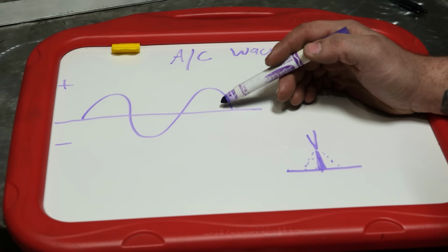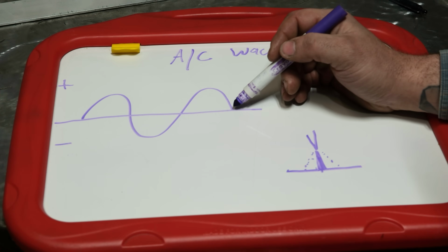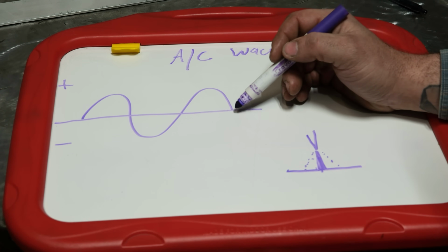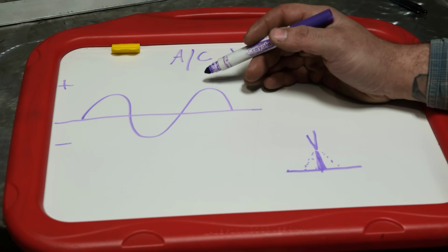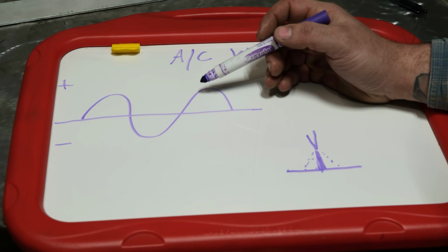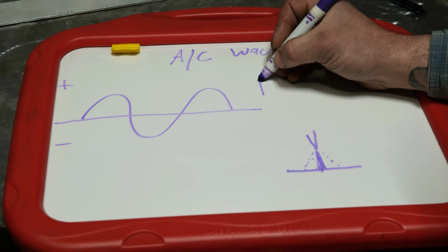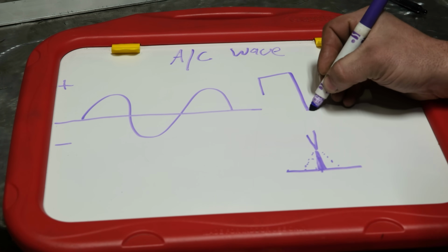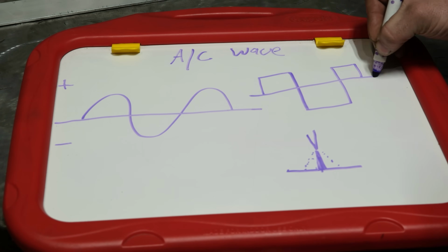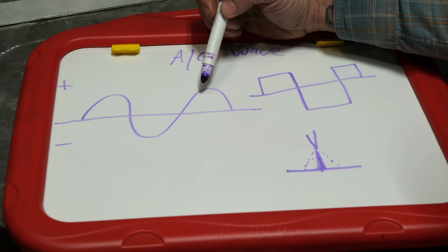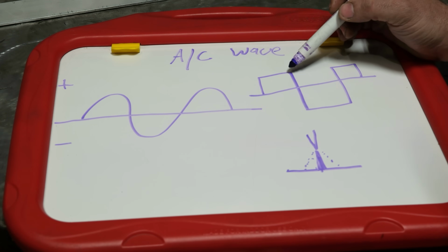This is depicting voltage. Virtually all older machines output on AC is a sine wave, because they don't convert the sine wave from the wall outlet into anything special on the output. Modern inverter machines can often manipulate the output to whatever they want. It's very common with modern machines to have what's called square wave. This is the output of the machine. This again is depicting voltage, and rather than being a rounded off profile like a sine wave, it is square.